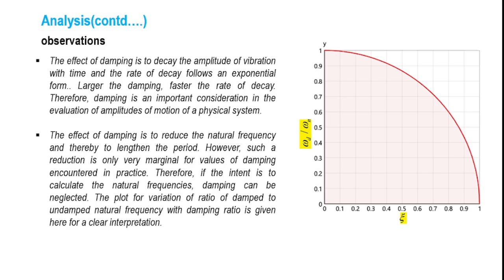Obviously, just like the free vibration, we will have two cases, that is both a damped as well as an undamped case. Now, here I want to tell you one very important thing. People might be wondering why we are discussing so much on the structural dynamics. Remember the basic understanding here, whatever videos 2, 3, 4, etc., whatever we are discussing is only a very brief discussion of the performance or the behavior or the response of the single degree of freedom systems. And remember, this knowledge is very much required for understanding or for deriving the equations of motions for a machine foundation.